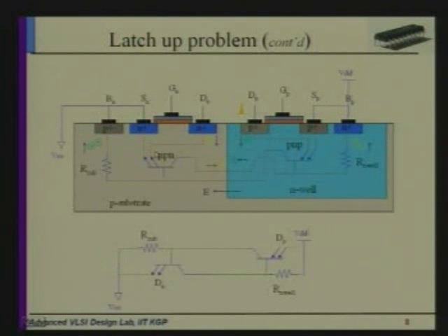That's why, if you see the circuit at the input side and the output side, if the output buffer is very huge, that means the drain area or source area is very huge. At that time, people prefer not to use the ESD circuit, because that MOS driver itself will take care of the ESD due to this lateral BJT. Let's see the characteristic of how the MOS helps with ESD.